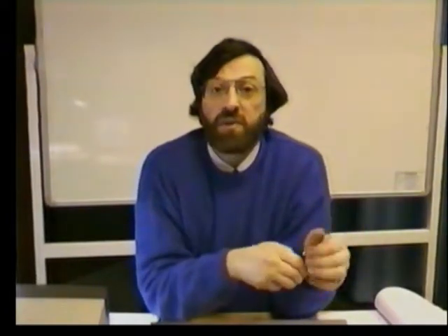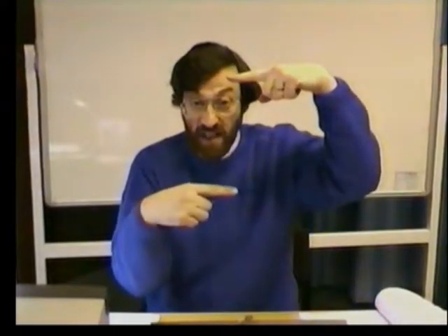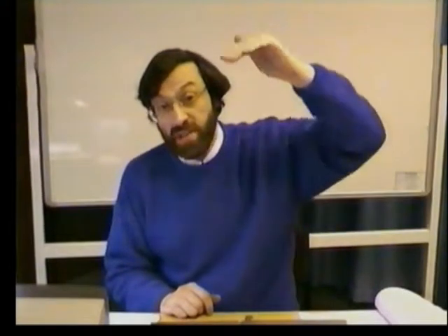So a hysteresis band is a way of stopping hunting in an on-off controller, and that is achieved by widening out the set point to be a band around the set point, positive hysteresis, negative hysteresis, and while we're rising, we pull it through the set point and then we let it fall back down again. So hysteresis is a way of controlling hunting in an on-off controller with a unidirectional system. That is, you can only actively drive it one way.